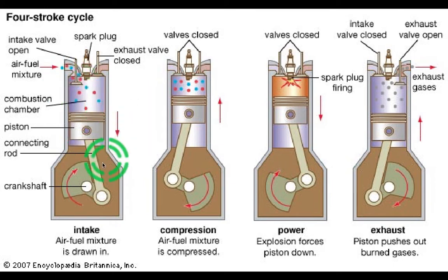So okay, your piston, the first stroke begins with the piston being at its top dead center, and it starts to move down, right? Let's say you are cranking up the engine, and the starter motor is actually trying to turn it, and it is moving down.